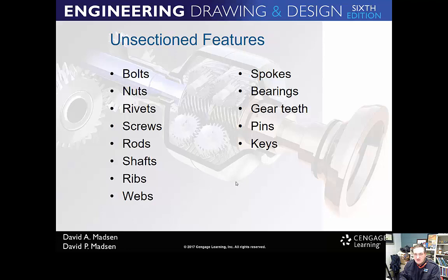And we're using a revolved section to do that, which we'll move along to here in a minute. So in general, spokes, you don't show them in like a full section, I guess is what you want to say. They can be, though. You can do a revolve section if you need to see the cross section of that piece.